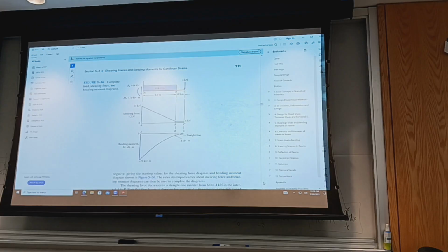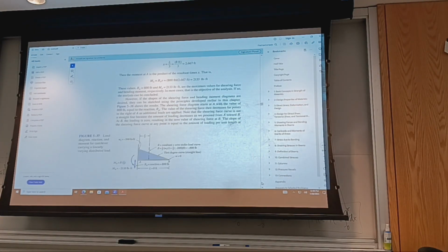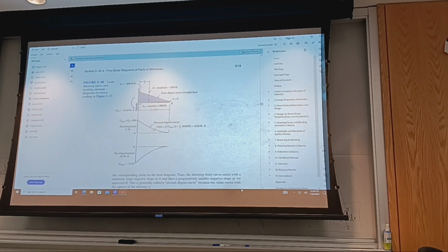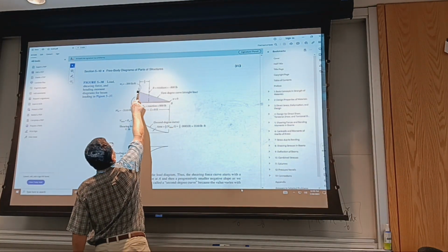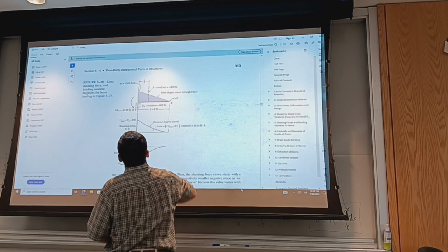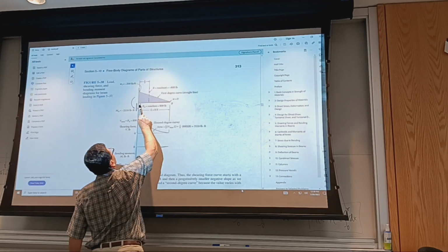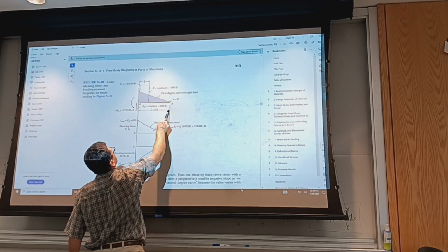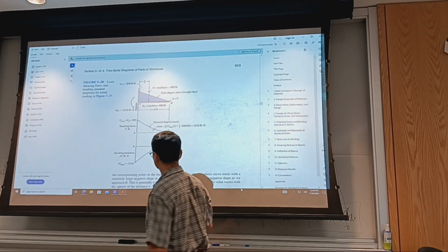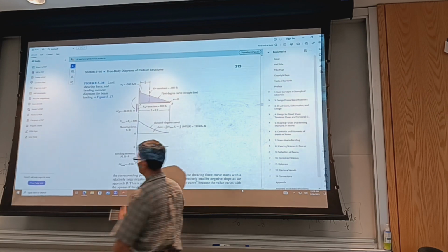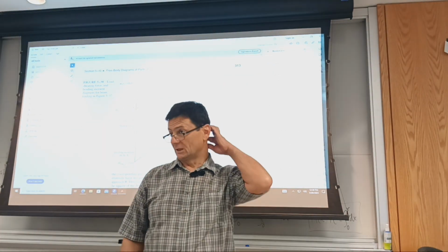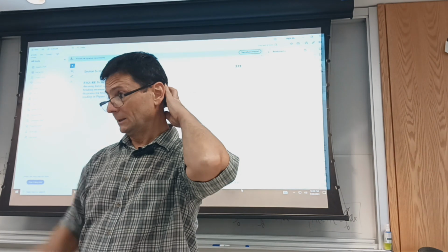and then if the concentrated load is tapered, first degree curve, straight line, then you would have the shear diagram. Remember, there is an integral, so you have this going. You can even write the equations. Oftentimes it just says this is a piece. This is the magnitude here. It goes to 0 at this distance. Beam can continue. So yeah, we have linear. It goes to parabolic, and the moment is going to be a third degree curve, a cubic. Okay, let me know if you have questions.